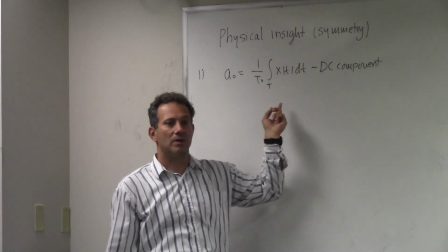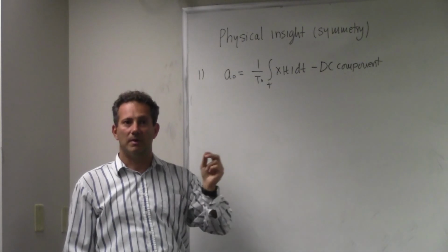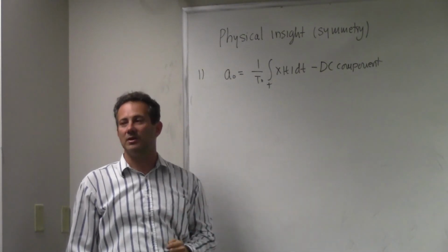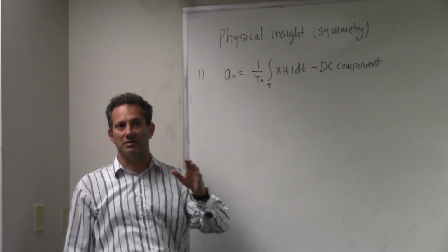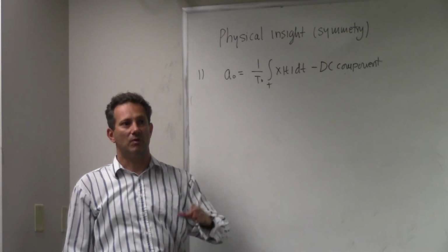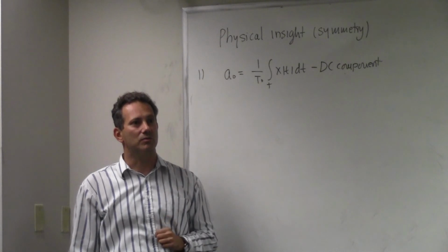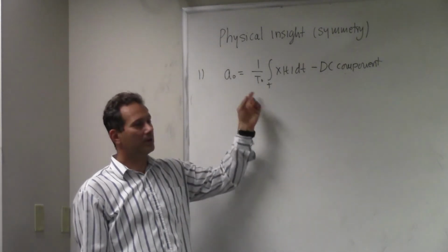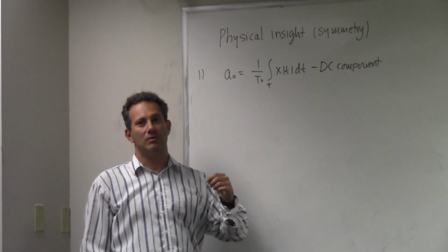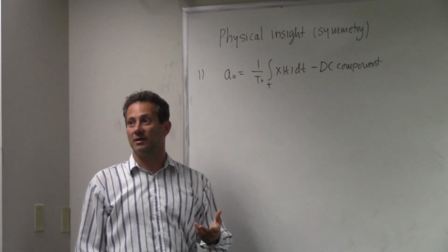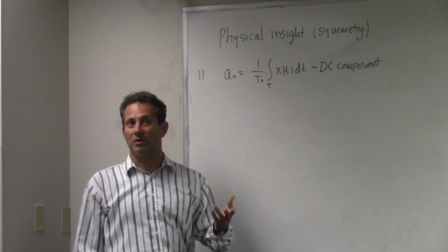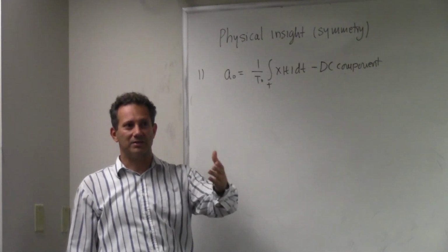Even in cases where you calculate A0, my advice is to guess what it needs to be. A lot of times you can eyeball the signal and say, okay, its DC component is between 1.5 and 2. Then you go and calculate, look at what you end up with, and compare it against your guess. They should be close, because we are pretty good at guessing DC values.